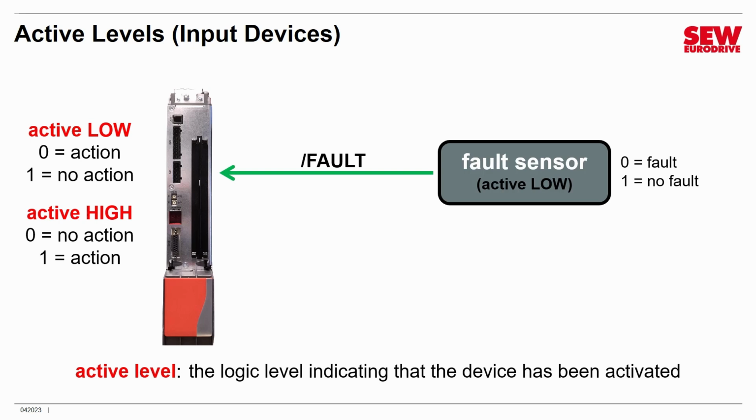So most critical sensors are active low as a kind of safety feature, meaning if the wire gets cut or their power supply fails, they'll trip the fault and shut things down usually. There's a technical term for this. It's called fail-safe. And what it means is that if a device fails, it will fail in the safest possible state.